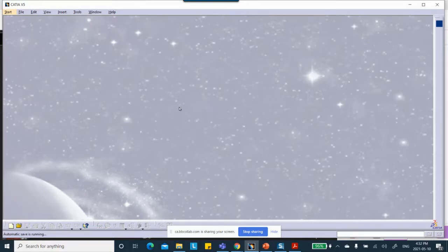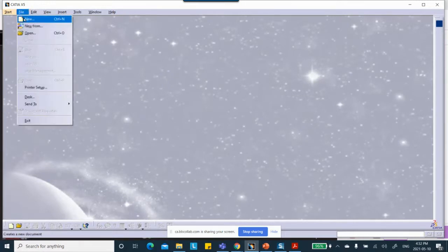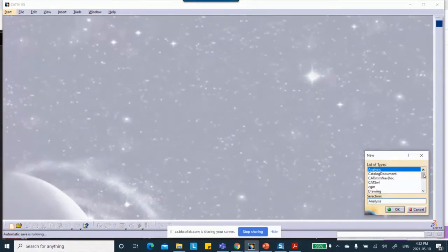First of all, what you should do is start with a part file. Because when you start CATIA, it usually starts with a product, and I have no issue with it. Anything that I do, instead of being a part, you can do within a product. There's no problem, except that products are for assemblies. We're not going to do FEA of assemblies for another 3 weeks. To make sure that you don't run into problems, particularly on a midterm, when you have a part, start with a part file. So I'm going to start with a part file, new, and part.